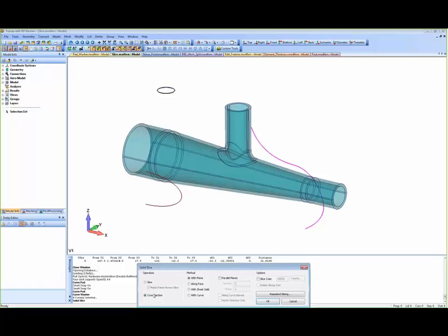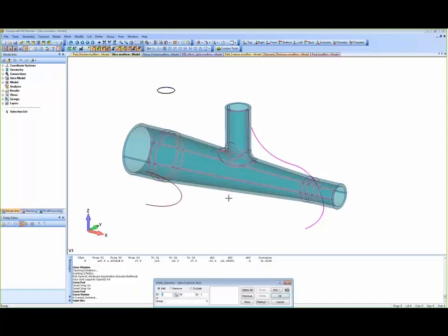One of them is this cross-section option. And you can also not only slice with a plane or along a face, but now you can select a sheet solid or a curve. So in this case, I want to create a cross-section of my solid with some of these curves. I'm going to tell it that I want to put it along a vector that I specify. And I'm going to hit the repeated slicing button, which allows me to slice the same solid with multiple curves.